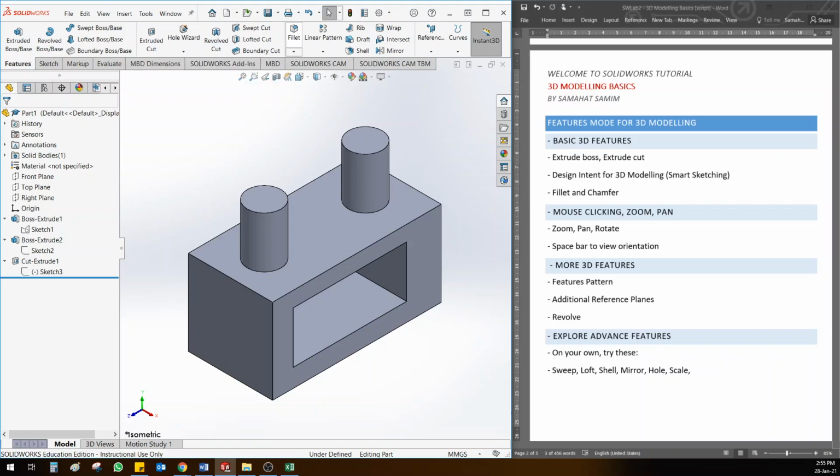Why do we need it? Because sometimes it's difficult to handle 3D parts. In reality, these are sharp edges. So this is a pointing corner. What if you catch it by your hand by force? It can pinch inside our hand. So what people do is they make the edges round. How can you make the edges round? You can use the fillet option. So let's see what it does.